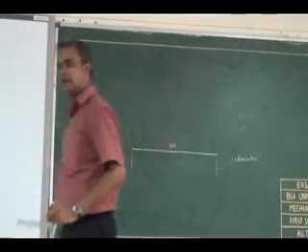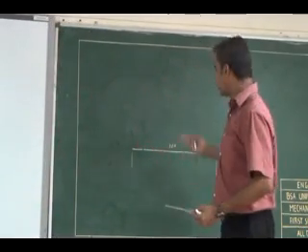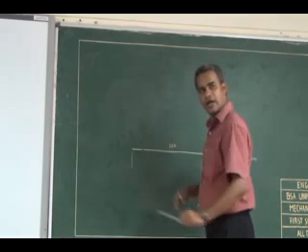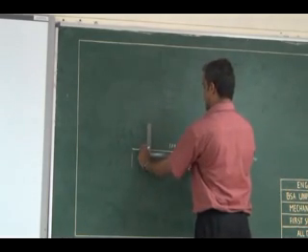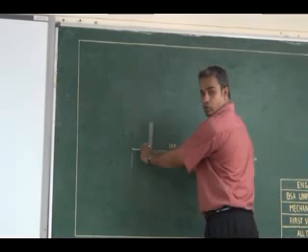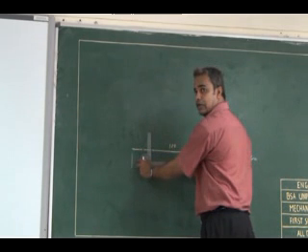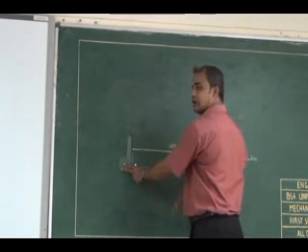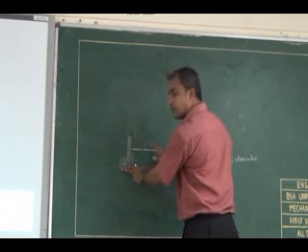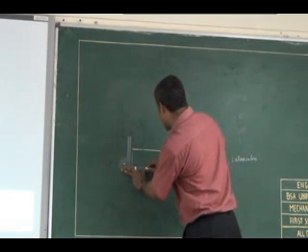Then there is another element in dimensioning, called the dimension line. The dimension line will be parallel to the object which you are dimensioning. So this is the object I am dimensioning, and parallel to that, again you have to use your drafter only. I align one scale of my drafter to the entity which I have to dimension, then I can move it parallelly. I have to draw a parallel dimension line which will have a minimum of 10 mm gap from the object line.